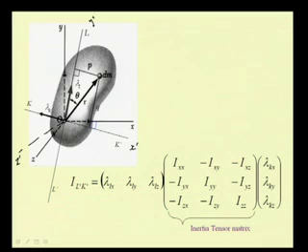So, now it is possible for us to rotate this axis and find these values of second moment for all these sets of orthogonal axes. And as in our discussion of the second moment of area, these second moments of the mass also reach some extremum value for a given orthogonal set of axes, and those we call the principal moments of inertia of the mass.